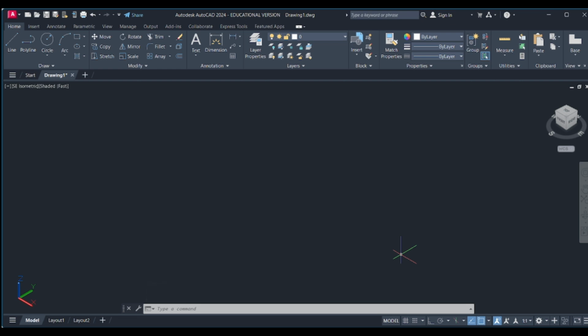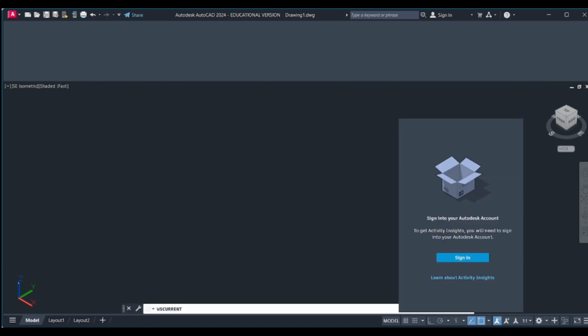Hello students, now we will learn how to draw the solid model in the AutoCAD. Now we will solve the question number 4. So go to the AutoCAD environment, go to the settings, change the setup from the drafting annotation to 3D modeling.